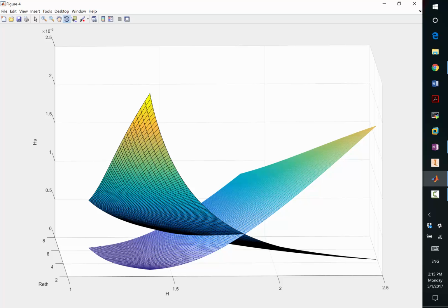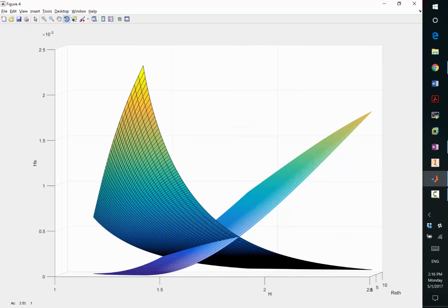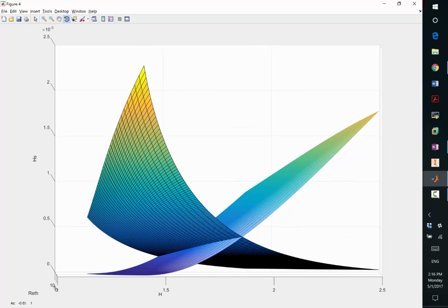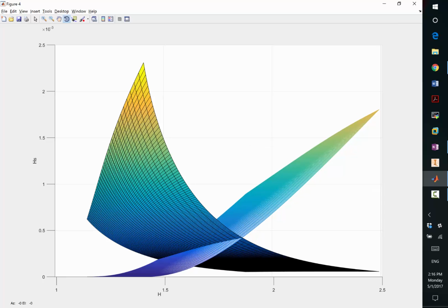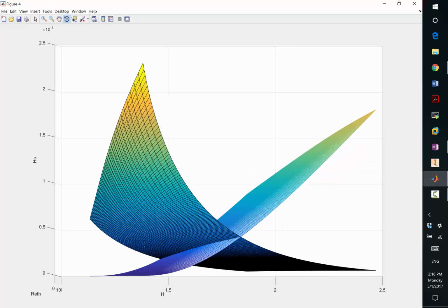And when you have a boundary layer that has a higher H or closer to separation, remember the inner layer becomes smaller and smaller. So when you have a turbulent boundary layer almost at separation, the inner layer becomes 0 because there is no skin friction coefficient, right? So the dissipation of the inner layer as you approach separation basically becomes 0, right? So we didn't get to the point, but when you are close to separation, the inner layer has no dissipation, and all the dissipation comes from the outer layer.